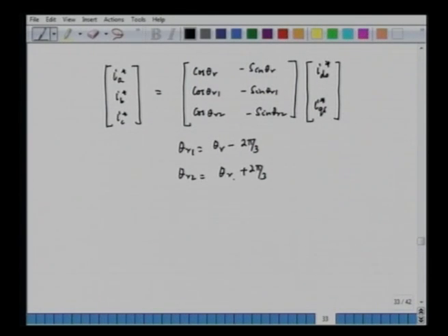So, this transformation transforms IDS and IQS into IA, IB, IC, which are used as the reference for the CRPWM VSI. Now, this is the aspect of implementation. The question that we asked a little earlier is how we are guaranteeing that in a vector controlled synchronous motor drive the response is quite fast. To understand that, we have to derive the equation for the torque of the synchronous motor. This we have already done in the past.